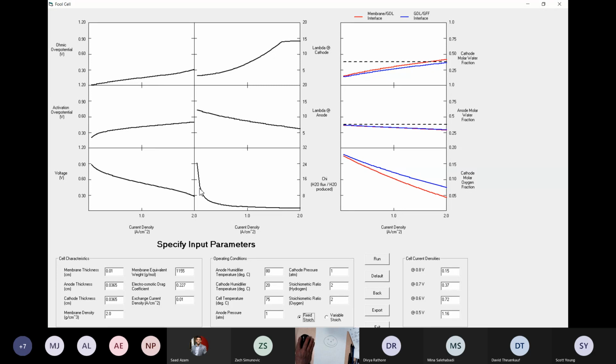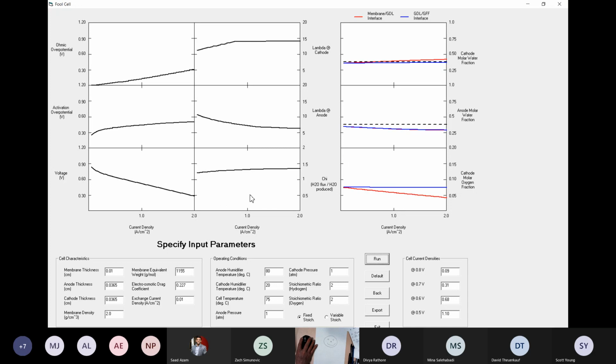It will mean we're not blowing a ton of humidified gas over the negative gas diffusion layer like we are in the variable stoich experiment. So we'll run. So now when you look at this water flux to water produced, it doesn't go up to 20 at low current densities. If there was a change in scale, now it's around 1 the whole way.